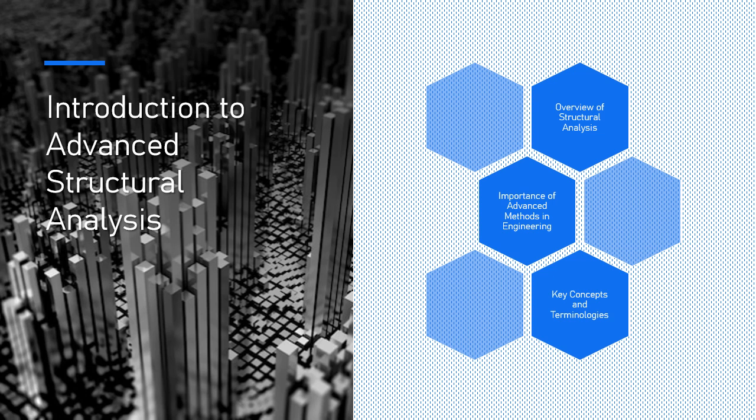Virtual work, a method for calculating displacements by considering the work done by internal and external forces. These energy-based approaches are particularly valuable for more complex analyses of indeterminate structures and can be integrated with advanced methods like matrix analysis and FEM.